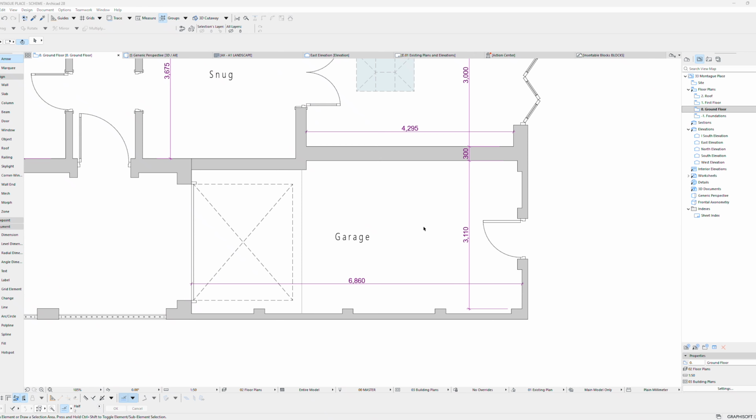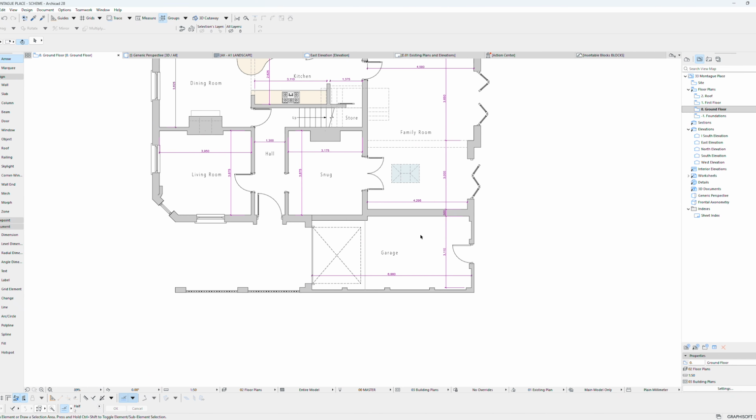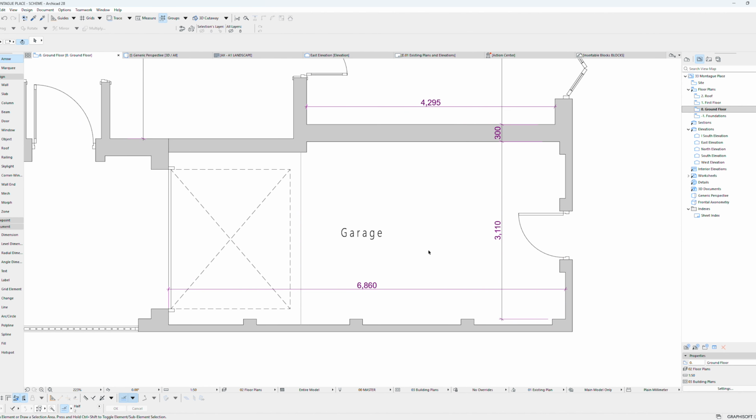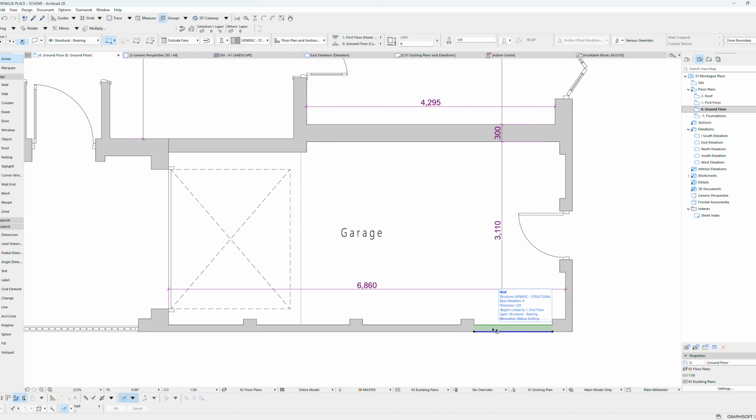Here's a little quick tip while I'm halfway through a project. I've got a detached dwelling that I've drawn as existing. This is the survey. And as part of the survey, I picked up that the garage was a single skin construction with piers. So I've just gone through and modified this wall by splitting it to create piers, so that the existing wall here is 120mm thick. By creating a split, I've then created a pier which is 220mm thick.